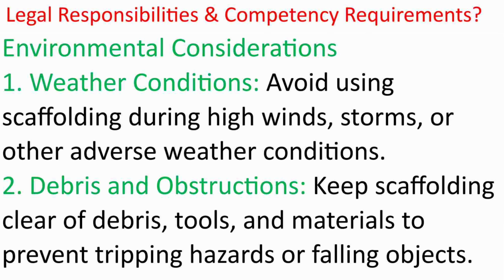Environmental considerations. 1. Weather conditions. Avoid using scaffolding during high winds, storms, or other adverse weather conditions. 2. Debris and obstructions. Keep scaffolding clear of debris, tools, and materials to prevent tripping hazards or falling objects.